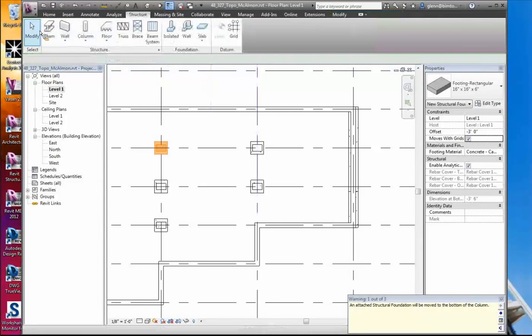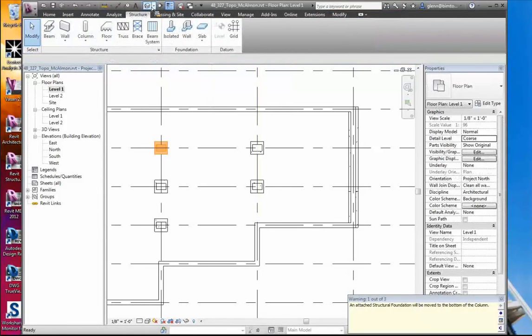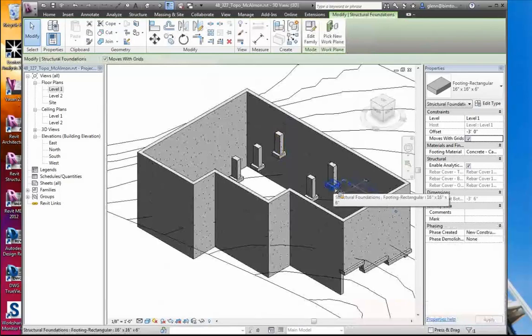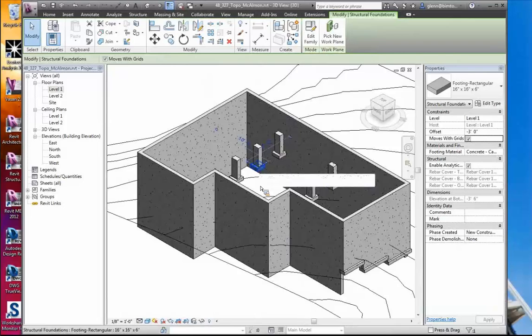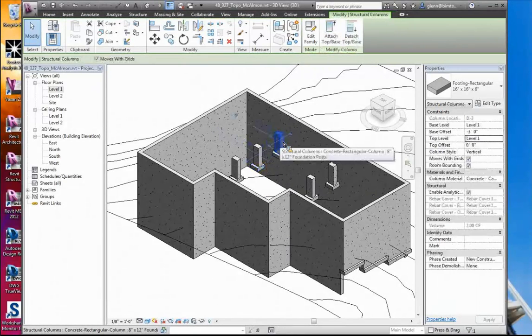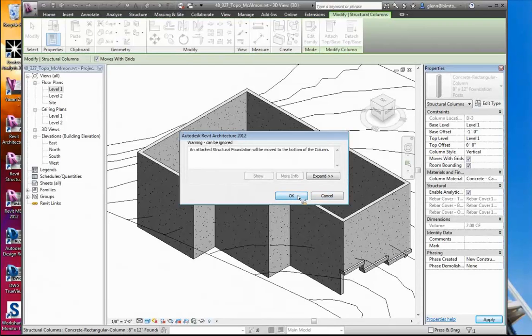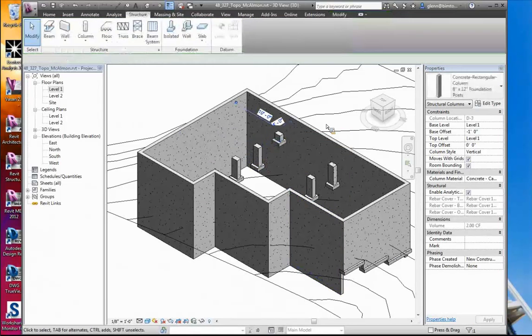Oh, that's interesting. It actually did a smarter thing there. Since I did the add column method, here I had to be very explicit about saying minus 3. If I switch to that add column method, it would do a better job of placing them wherever those columns would end up. So for example, on this column, if this was only minus 1 feet, notice it's going to go ahead and move them in there.